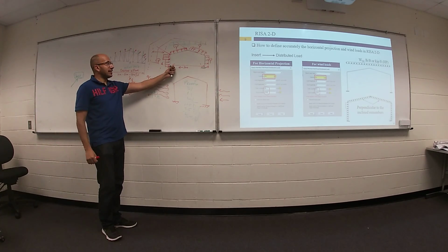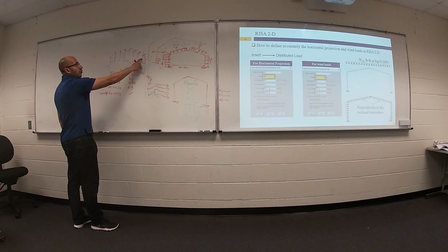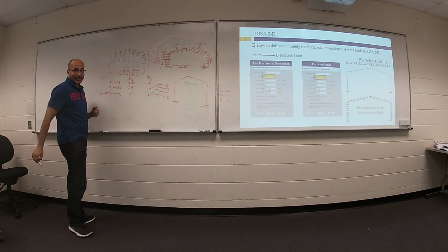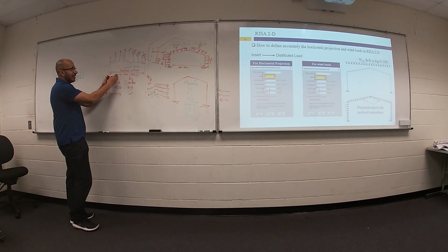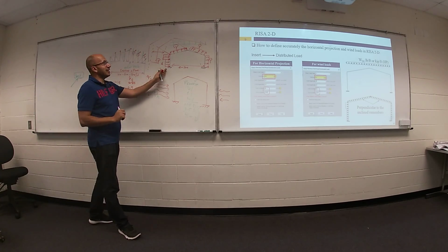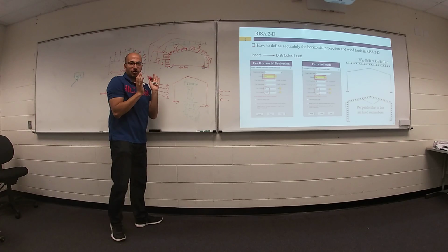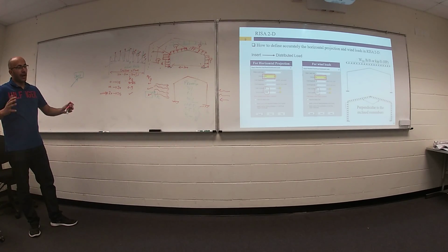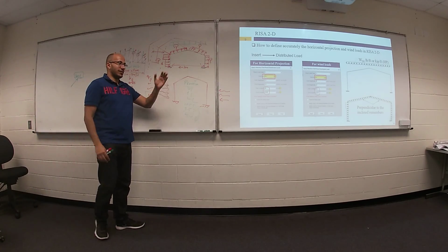We recommend this one for small area because fabrication of all of these members and all of these connections is not easy. But it will be economic if you have a larger span. This one is very simple if your area is small and your span is small. Okay? You got it? But in our course, it's up to you. In your project, you can decide this one or this one. It's up to you.